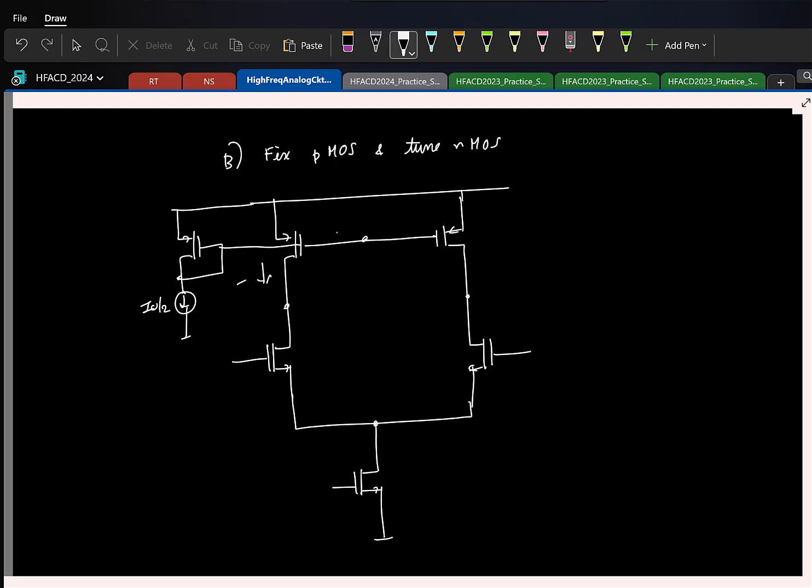So let us say this is fixed to some I0 by 2. Now let us say I make sure that the current flowing here is some I0 plus 2Ix. That is, it is not equal to I0, but I can make sure that it is greater than I0. Simple. Let us say I bias it to some point so that the current is greater than I0, and let it be I0 plus 2 times Ix.